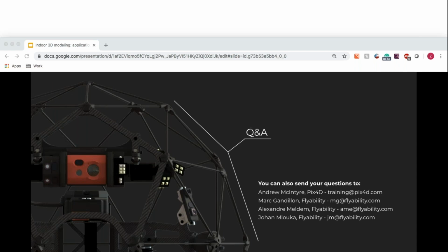And as soon as they did that, because their reconstruction was georeferenced using the same set of ground control points that were defining the same coordinate system as the rest of the project area that had been reconstructed previously, everything was, even though they weren't connected to each other, by definition aligned correctly relative to each other because they used a common set of control. So that would be the most logical way to do it. I hope that answers the question.